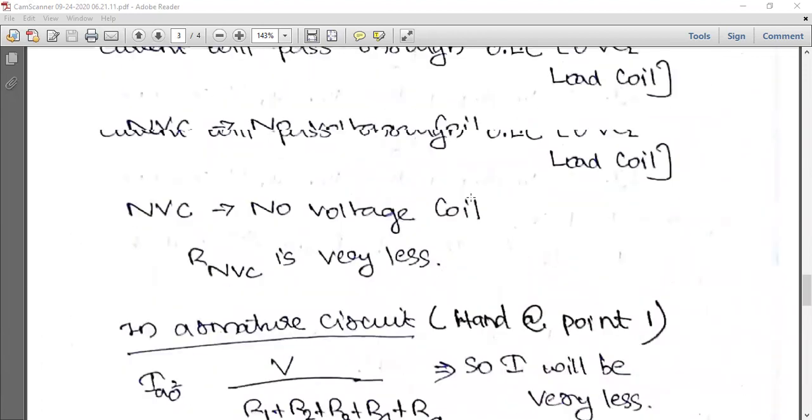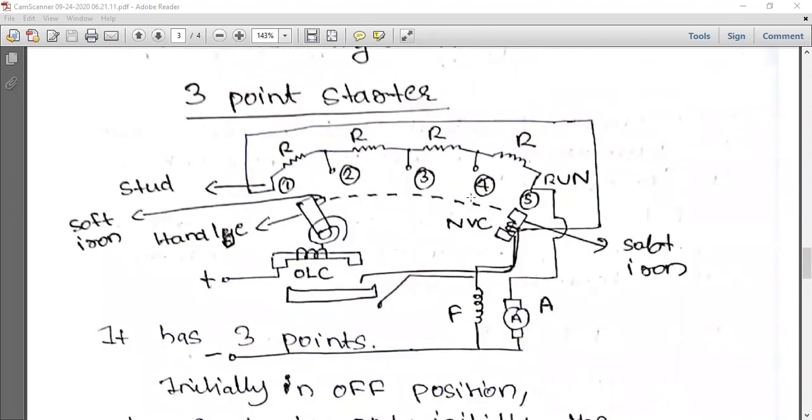When the machine is de-energized, the handle should come back to the old position. If it stays here and power suddenly comes, the current will be dangerously high, because when we restart, we need the same process to happen again, that is the gradual decrease of resistance.